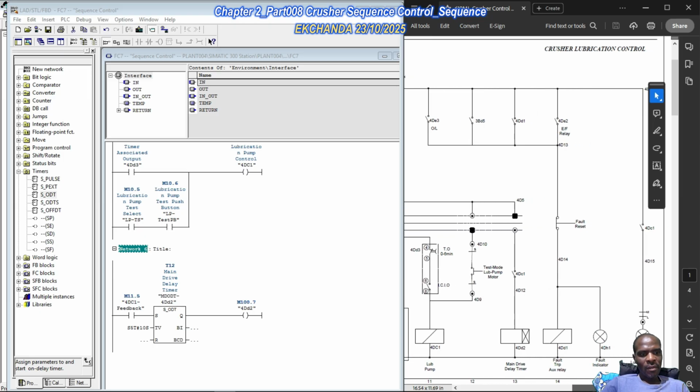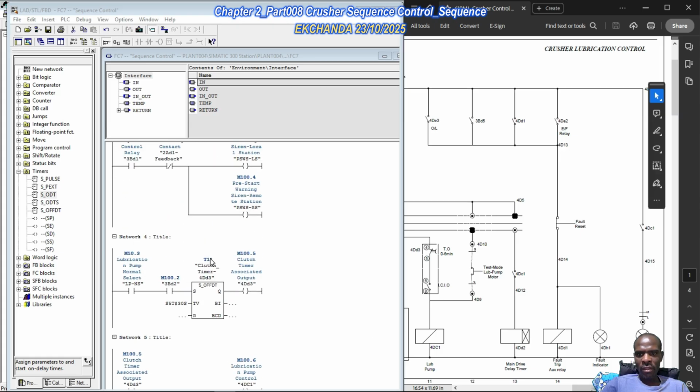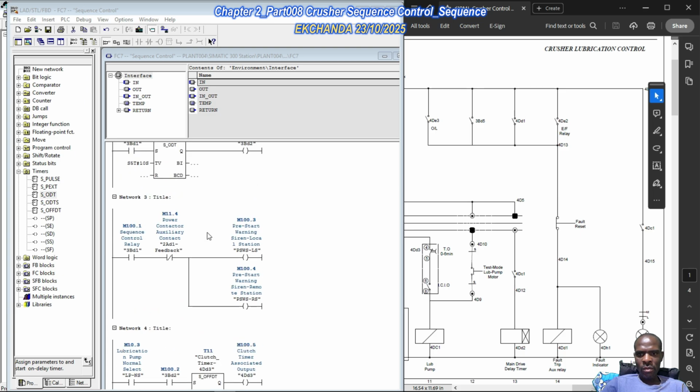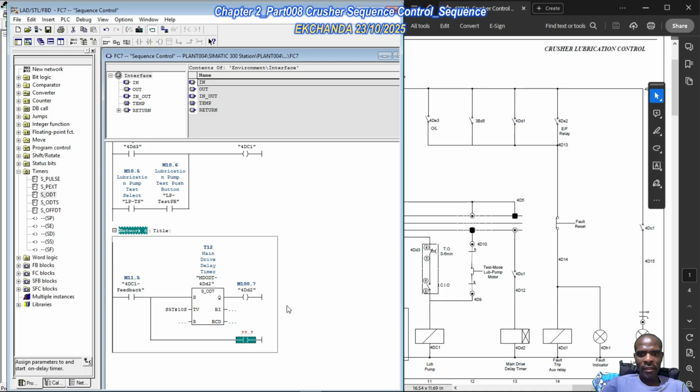protection side of things. But when we talk about the loop pump running, you will notice that it depends on 4DC1. So for the loop pump running, this one as 4DH2, we need the feedback for the loop pump, the 4DC1 feedback. This same feedback here. If we wanted, we could have just done this. Okay, then put an output coil there, and then we could say 4DH2.